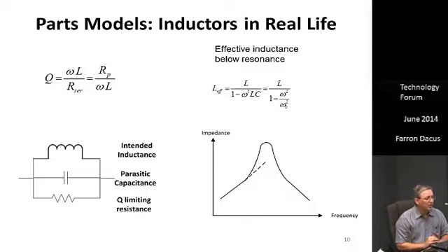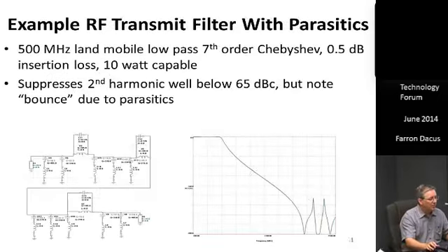An S-parameter simulator may let you put in self-resonance or Q directly, and it'll run that model internally. But if you're using, say, SPICE, then you have to put that exact model in, or even something a little more sophisticated for some parts. So here's an example. It's kind of hard to see, but I've got a low-pass LC filter here. Here's the intended parallel capacitors, and then series inductance. And it's got the parasitics inserted for those parts, and then here is our low-pass function.